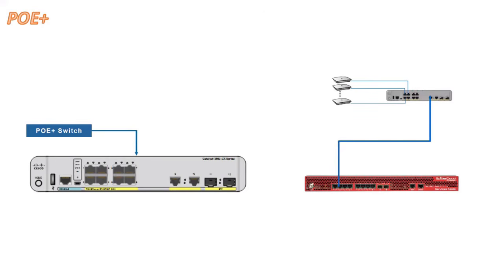Then we have these PoE plus switches, right? Radio nodes get their DC power using power over Ethernet on copper cable using PoE plus switches. The maximum PoE plus cable run is 100 meters, or you can say 328 feet. And there will always be a Cat6 cable, or twisted pair cable, between the PoE and the radio node.